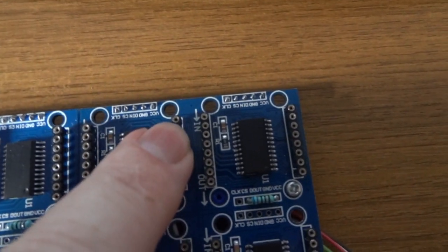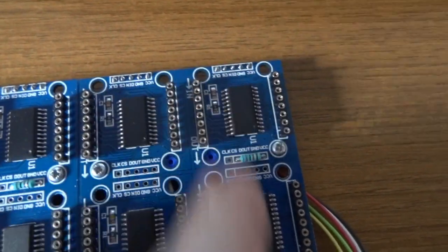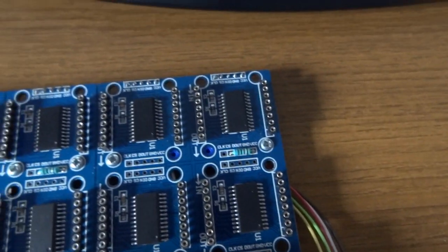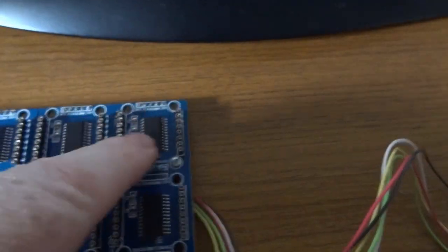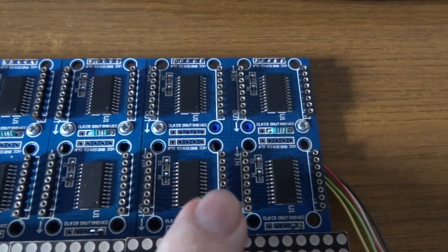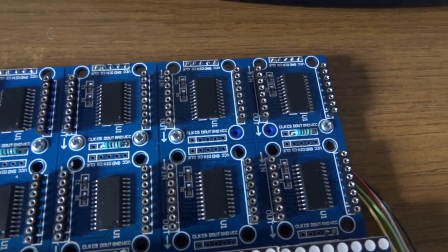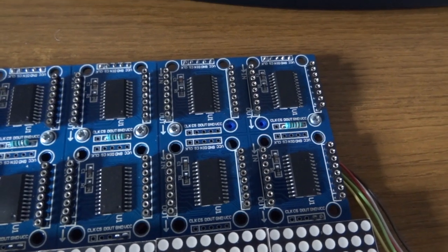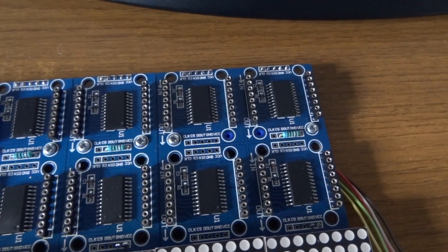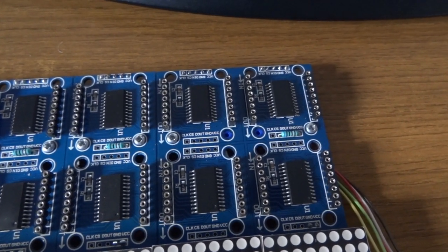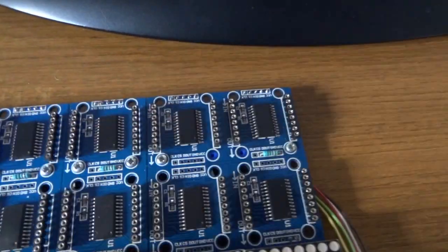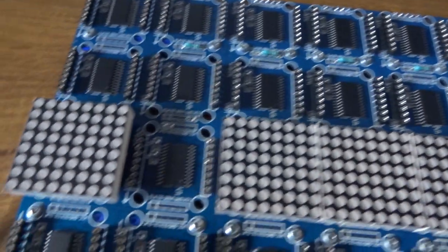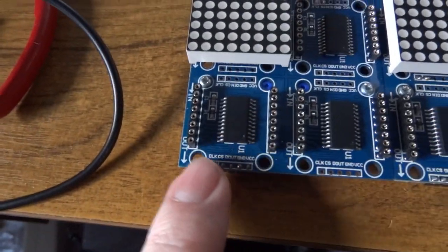If you're making one of these, you notice that this is the input end of things with the arrows pointing down, so the modules are running that way, and the first input cable from the microcontroller goes in to what will be the top right hand corner. But bear in mind these are shift registers, so in terms of the data that you clock out, it will go through these 4, then these 4, and so on, and eventually end up at this bottom left hand corner.